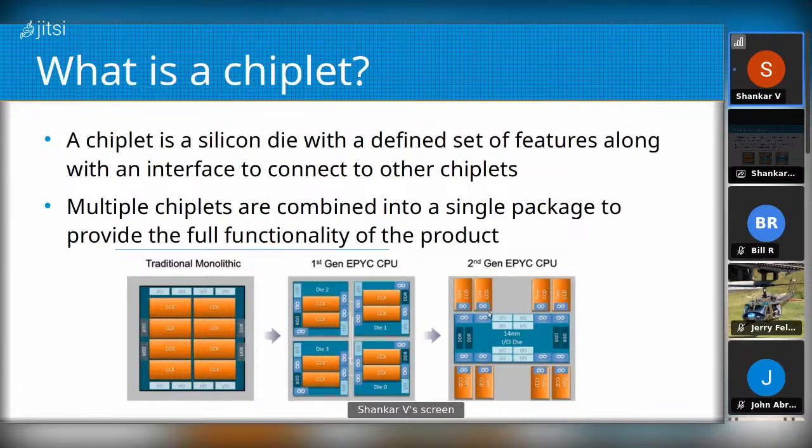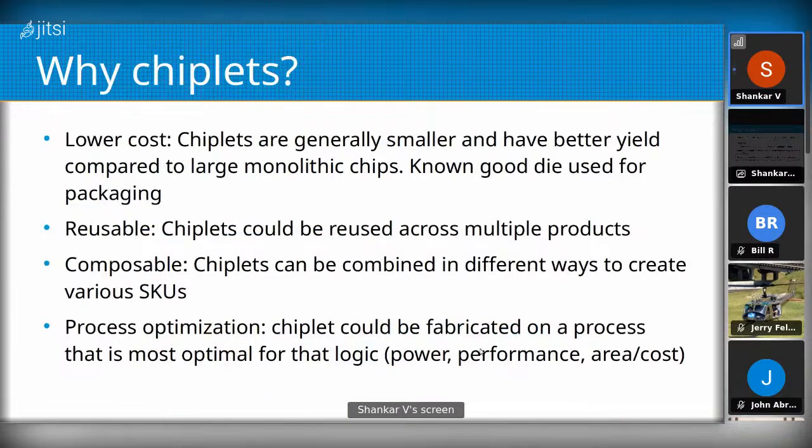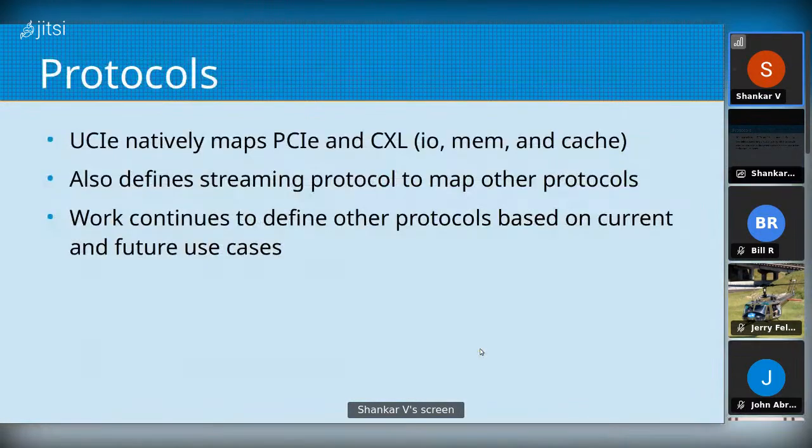It can't be less than a certain width if you have a large number of wires. So depending on the number of wires that have to connect across these two chiplets, there is this beachfront that you have to determine. That determines when you design these chiplets how much area, how much space here I need to allocate for these die-to-die connections. So that's another important consideration